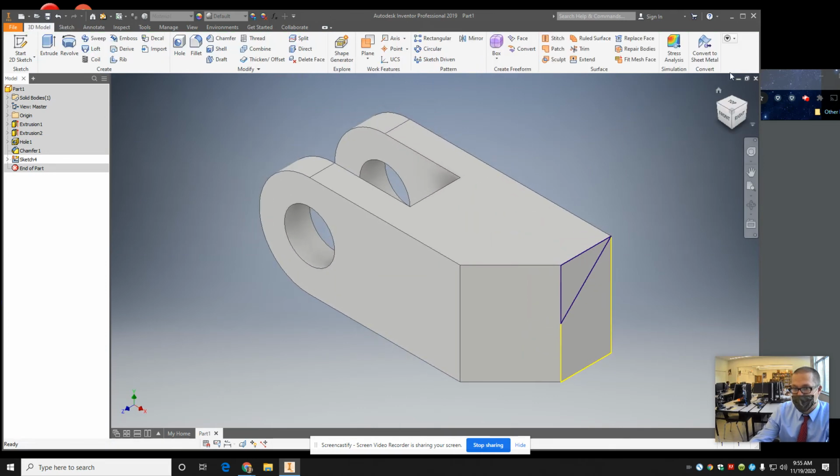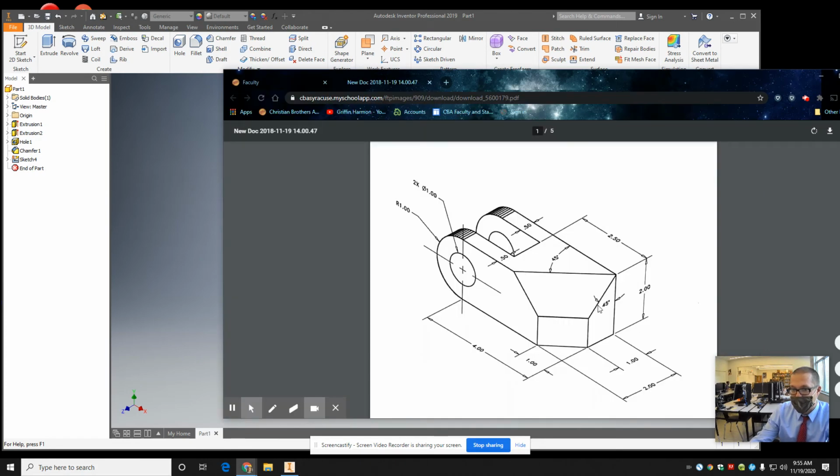Let me hit finish sketch so you can see what I'm doing. I am tracing this corner because I'm going to do a loft from this corner straight over to this corner and blast off that material. It's going to be a cut loft. All right. So actually, does it go down halfway here? I don't know, right? But it's 45 degrees.